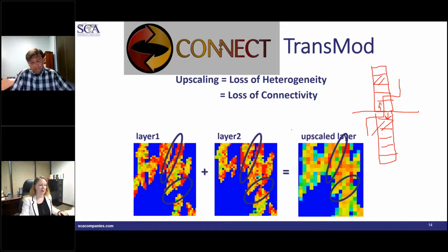Okay, the next question. If we have a complex DFN for naturally fractured reservoirs, will the autogrid be able to capture the effects of the vertical heterogeneity? As we saw, it's a 1D simulator. Yes. So the answer to that question about the 1D simulator, which is the unconventional simulation, is that we have the dual porosity option. So the way we actually use the 1D simulation, when you have a dual porosity model,